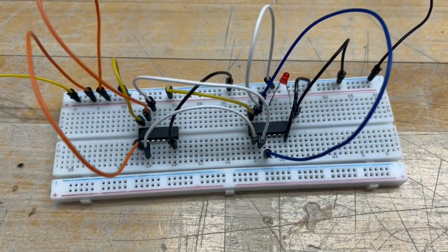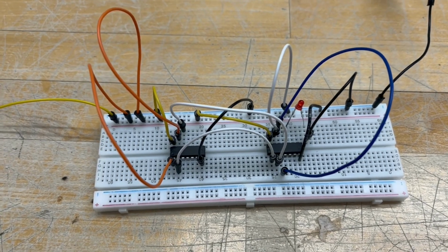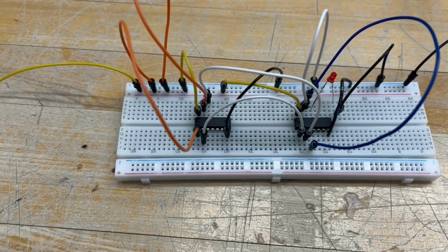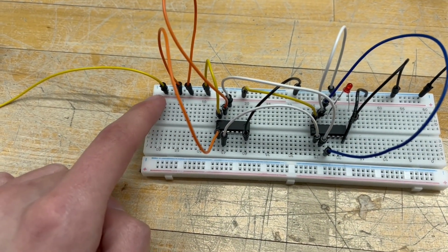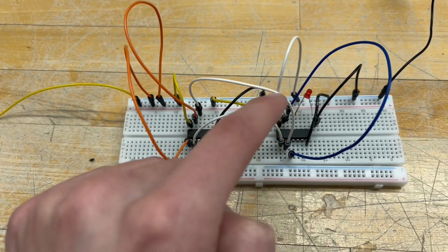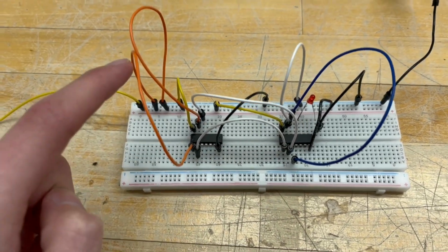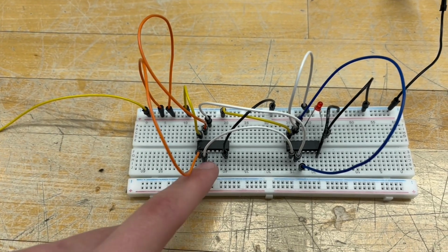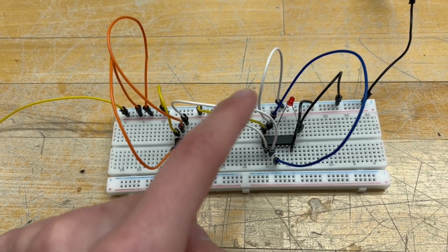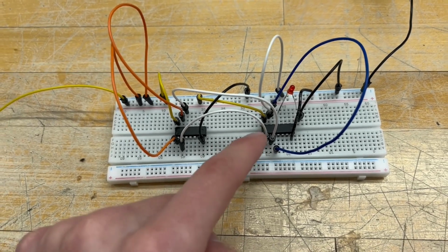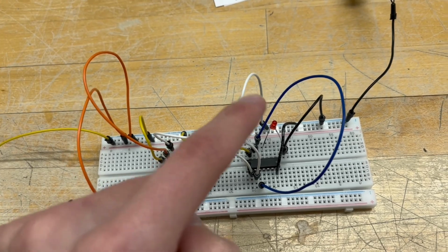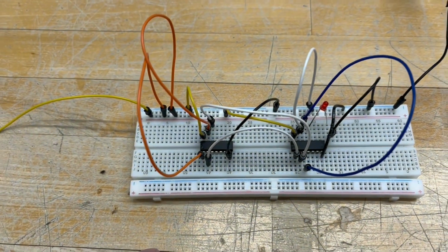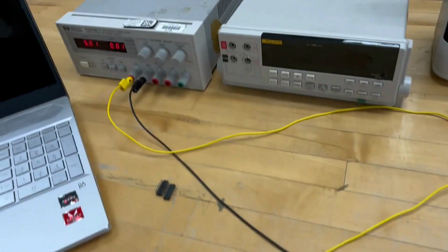So by default, I have the LED being turned off because X and Z are both plugged into the 5-volt voltage source, and Y is grounded. But since X and Z are being inverted, they are both outputting 0. So it's 0 and 0 being added together, plus Y, which is also equal to 0, which is why the LED is turned off. You can see it is plugged into the 5-volt source and it is on.